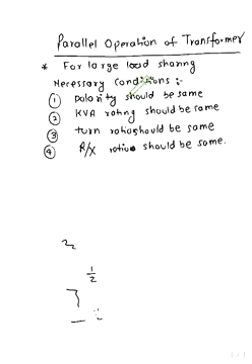Their windings will be connected to the supply side and the load side. Since both are in parallel, their polarity should be the same. The kVA rating should be the same. The turns ratio of each transformer should be the same, and the internal resistance to reactance ratio should be the same. So these are the necessary conditions for transformers connected in parallel in industry.